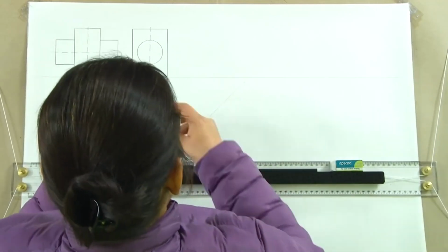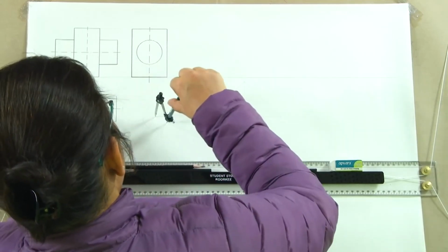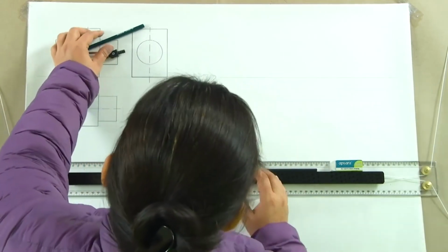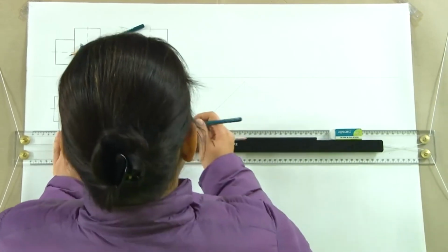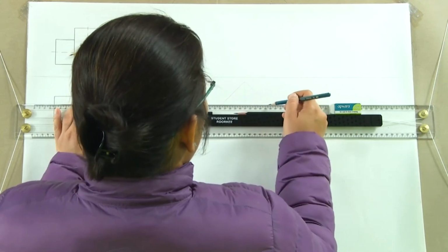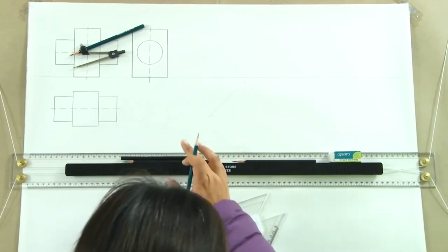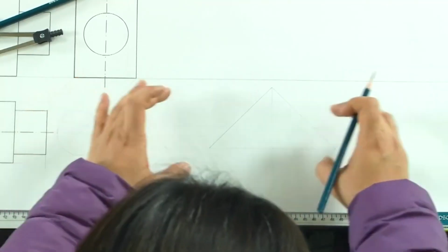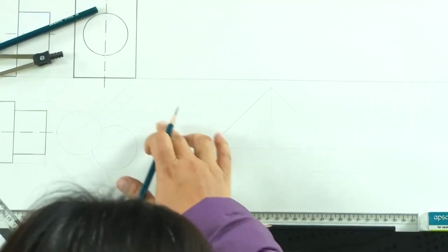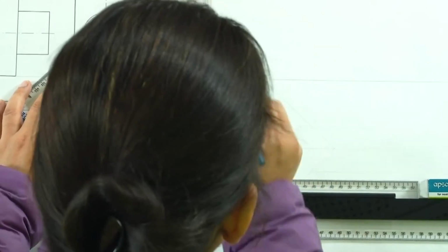we will just draw a reference here. So, since it is parallel to VP, we will be seeing a rectangular shape passing through this. So, what we have is this circular cylinder passing through this. Now, right now it is assumed to be parallel to both HP and VP. So, it is appearing as a straight rectangle, but I am not drawing the ends as of now because it is actually not parallel, and we will draw it once we draw the VP.